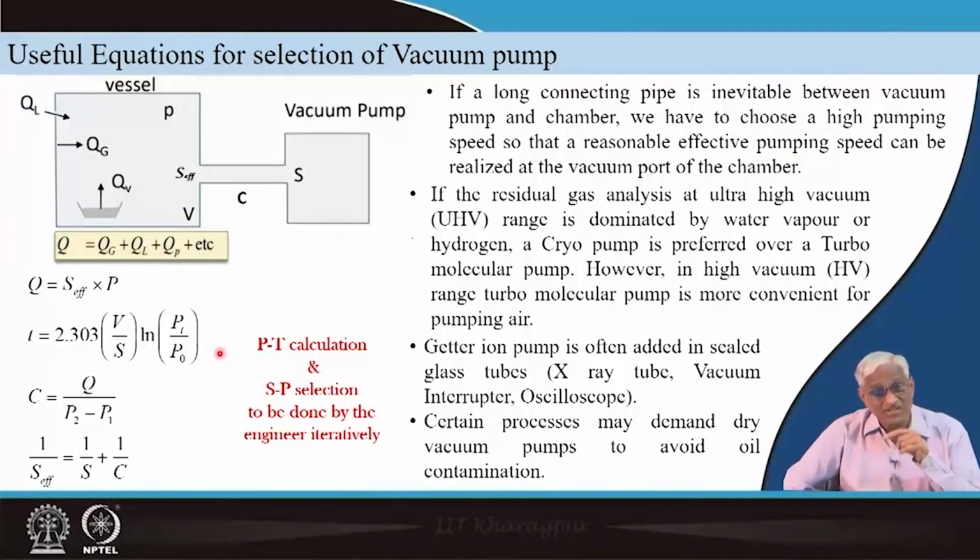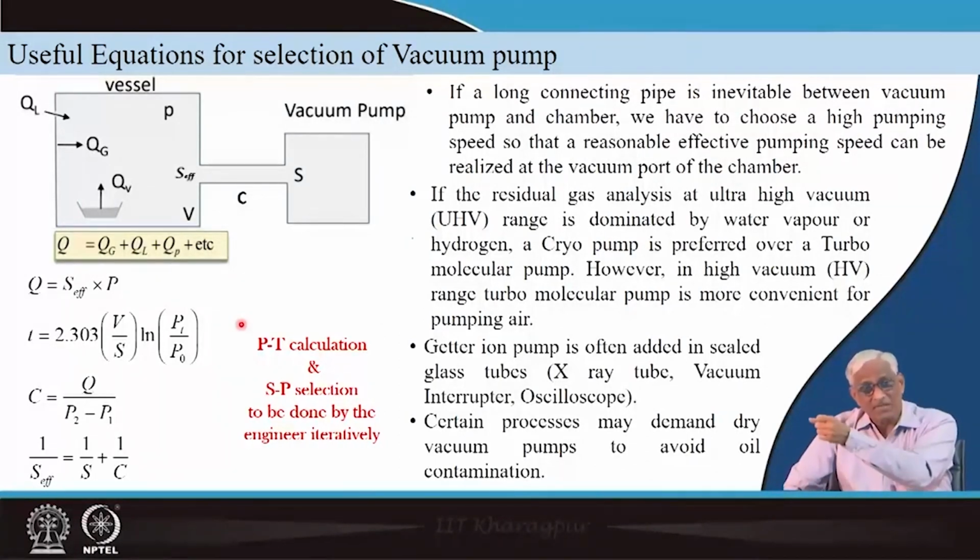Because initial evacuation to 0.1 torr and treating and ion etching, cleaning, holding and with a magnetic arm opening the gate valve, all these operations should be done fast. That is the weakest link. If you take longer time, you are gone.